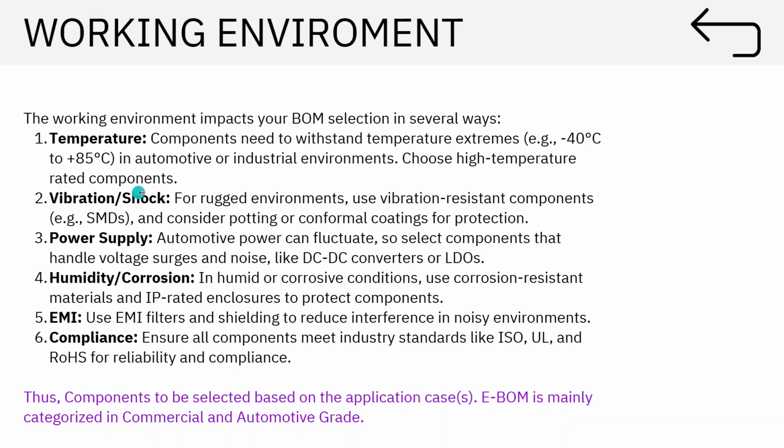Then vibration and shock. Let's say you are considering SMD parts and you want to mount this directly on the chassis of some vehicle. That means you have to have potting. What potting basically is: you would have seen hardware where some resin material is there, so that there is no movement of the components and no air gaps. You have a solid part around the components, so that in case of any vibrations, there is no room for those components to move.